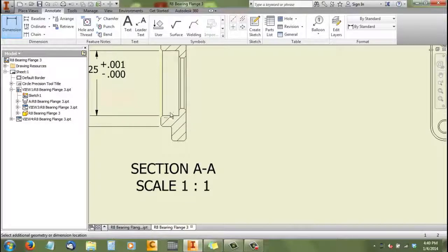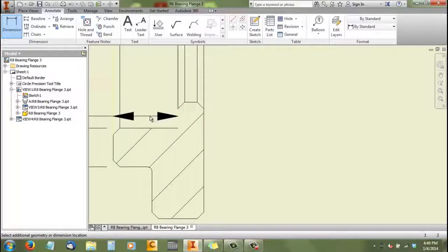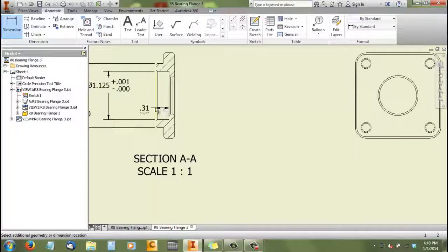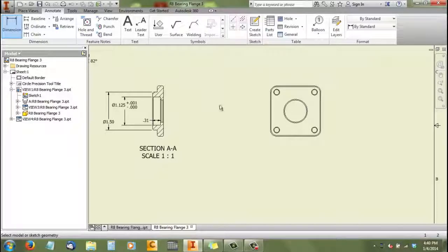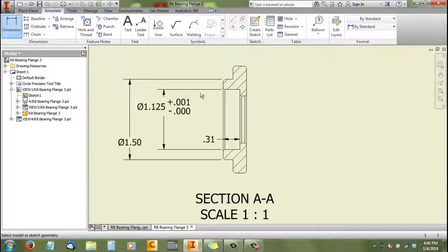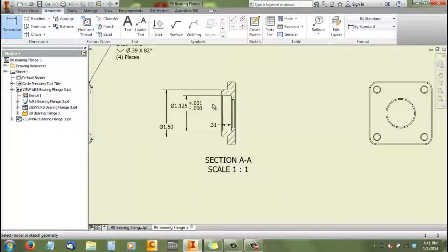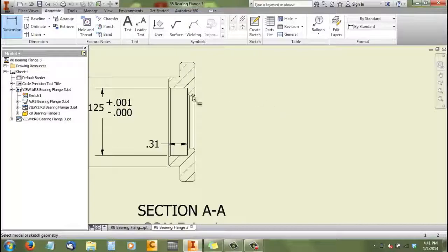So just about everything else on this part is plus or minus 0.10 of an inch. And it would in reality be made quite a bit more tolerant than that. But so that gets us the OD, the ID of the boss, the depth of the boss. And we have this through hole here. I'm going to call that out on the back side of this view using the same strategy. Only because you like to look in, there we go.